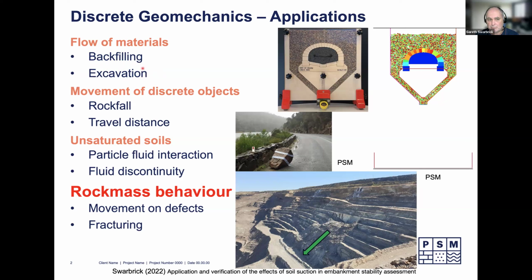I'm going to show you a little problem we had recently with tunneling in Sydney, where we had a very old sandstone lined blockwork drain, which was heritage protected. All of these sandstone blocks were not structurally connected to each other. They were simply loose blocks arranged in an arch. We did quite a bit of modeling on this, but what I'm showing you here is a 1:20 scale model, because we ended up having to do a scale model to convince ourselves that the modeling we were doing, which was based on continua, had some defensible component to it and was reflecting what we might actually see in reality.